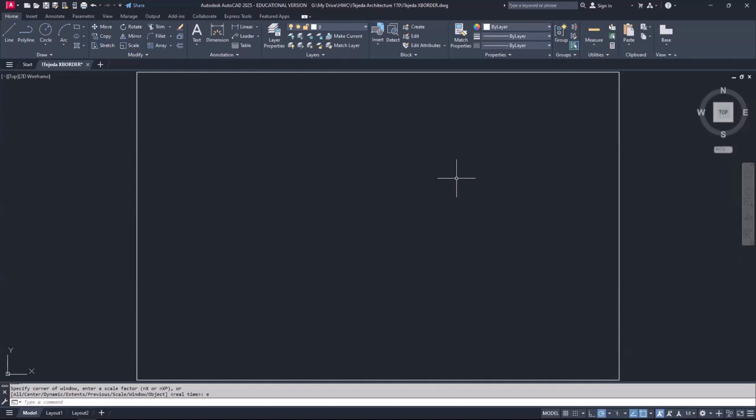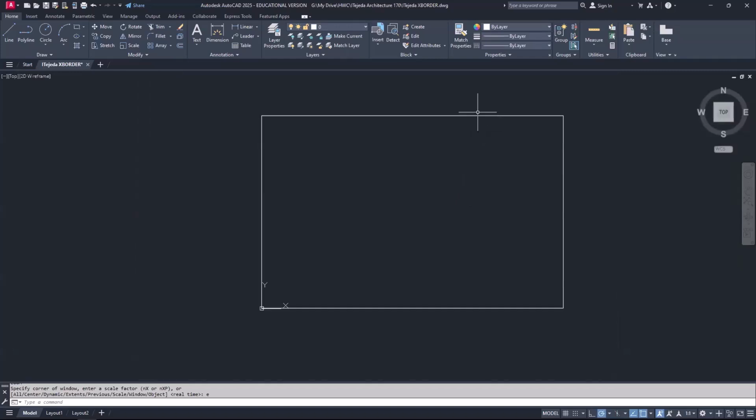And I'm going to say that we're okay getting away with about a 1/4 inch of a margin all the way around. I have an architectural scale over here that I'm looking at, and 1/4 inch is a good distance to keep. So since this is a polyline, I'm going to zoom out, and let me tap the escape key. I can go ahead and offset. So I'll type O, enter, and the offset distance is simply going to be 1/4 of an inch.